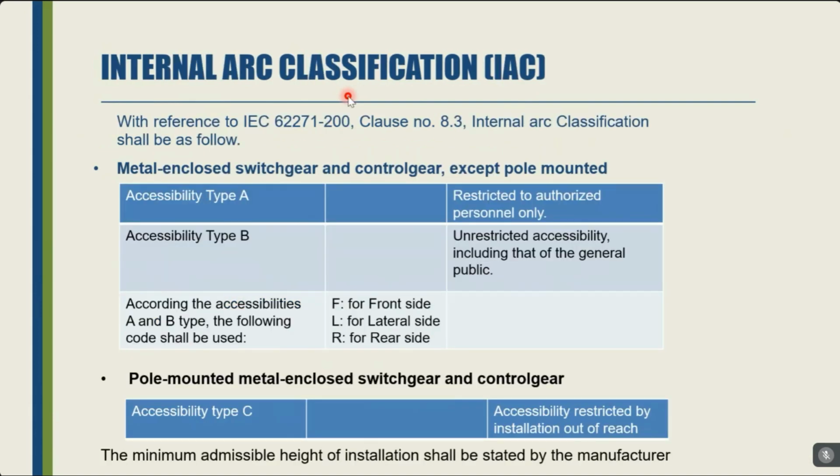Now a very important point is internal arc classification. In most American organizations or companies, the maintenance of a switchgear usually happens online, when the panel is live.